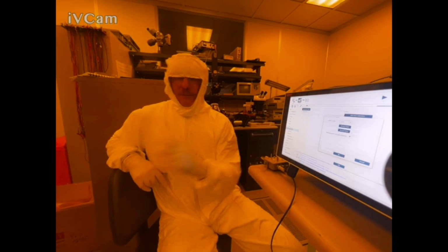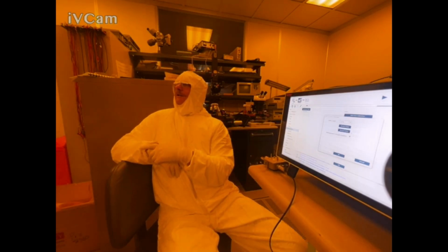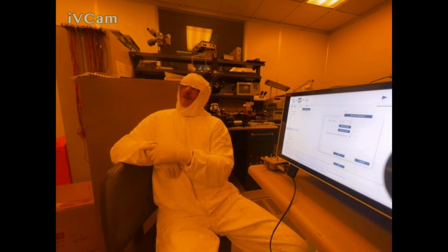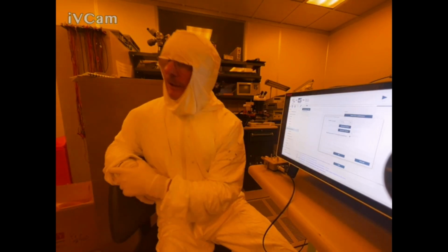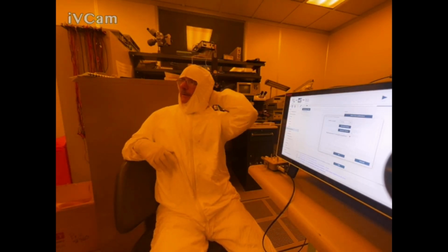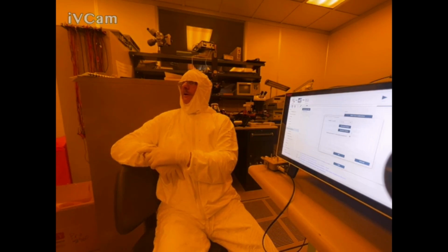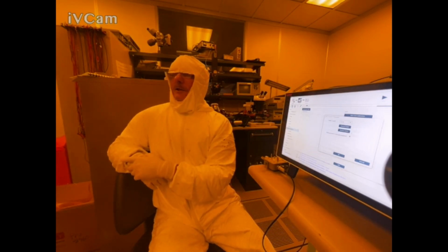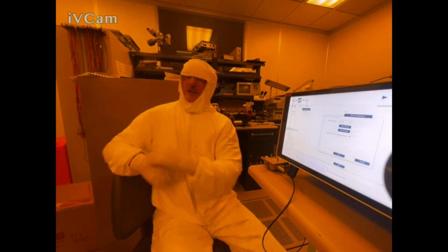The short compensation is for large capacitances. So unless you're measuring large capacitances, bigger than nanofarads, you probably don't have to even worry about that. Don't even do it. All you really need to do is the open compensation. Okay? So that's what we'll do.